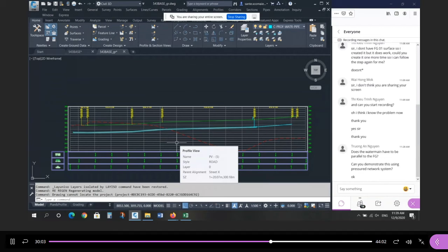You go through the design and then you review it and you review it, and it's a cyclical process, right? Because the road design is going to dictate where your pipes go, and where your pipes go is going to dictate where your road needs to be, and the road is going to influence your grading, and the grade influences how deep your pipe needs to be. So it's all interconnected. You have to start somewhere, right? But as you go through the process, you might find you have to revisit something you did prior so that everything works together. So it's iterative, right? You revisit everything on an ongoing basis.